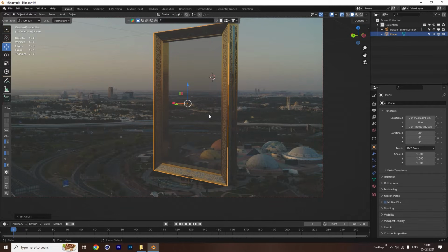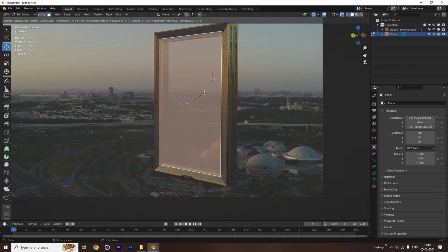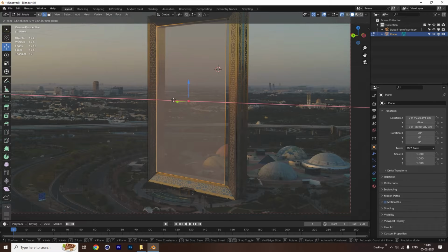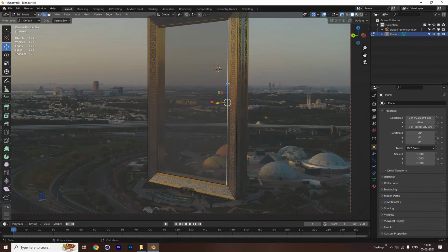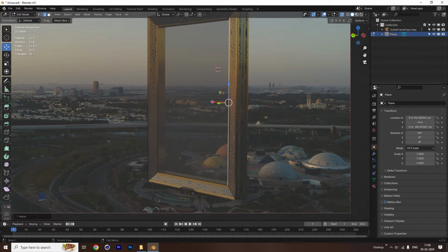You can go to geometry and put the geometry origin at the center and press Ctrl A and scale the plane. Now you properly insert it. Now we push the plane a little bit on the Y-axis to put it a little backward.